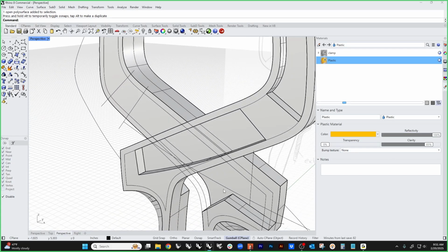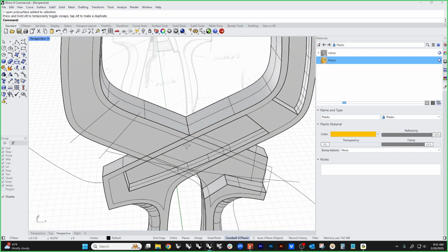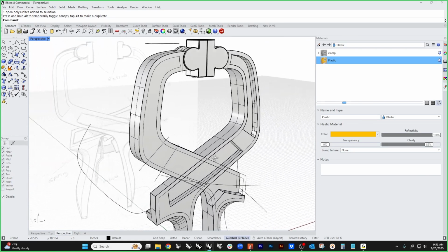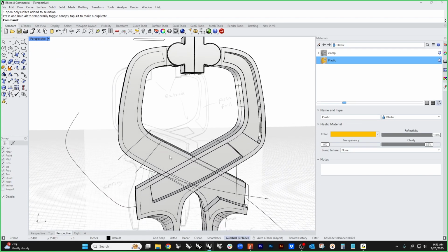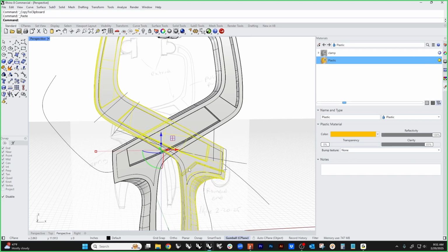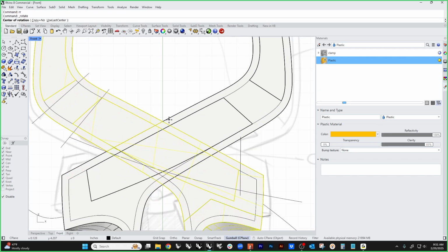And we have some intersecting parts, and it looks like we need a little bit of clearance. Actually, that's closed, so when it opens, this guy needs some clearance as well. So if we copy, paste, go to the front view, rotate between this point and this point.